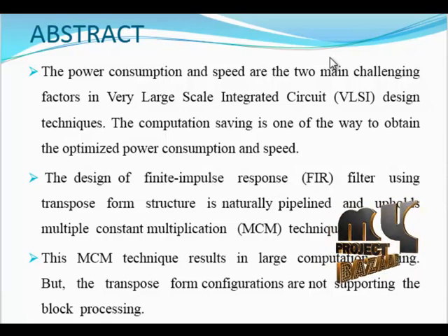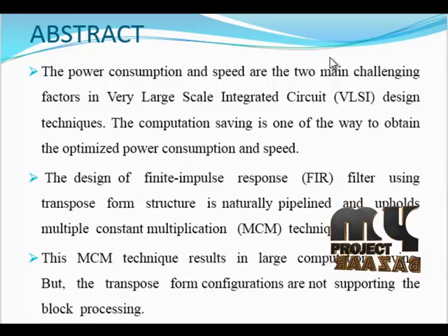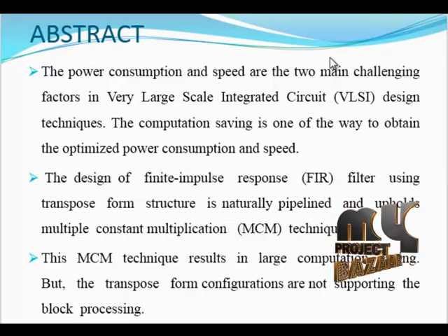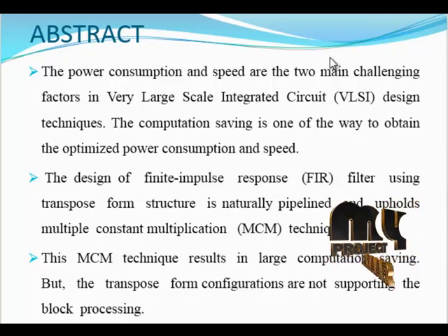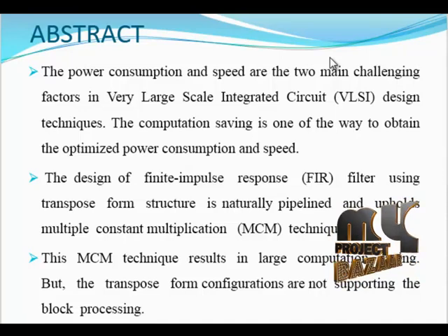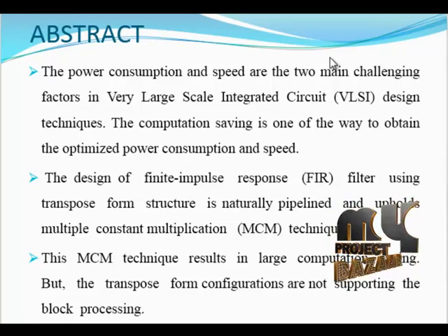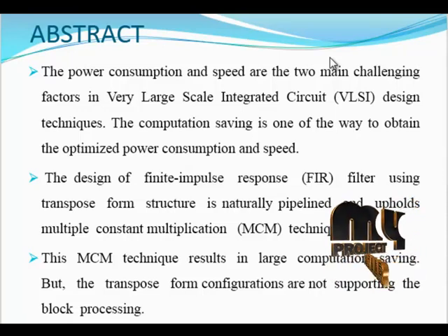There are several applications where the coefficients of FIR filters remain fixed, while in some other applications like an SDR channelizer, separate FIR filters of different specifications are required to extract one of the desired narrow band channels from the wide band RF front end. These FIR filters need to be implemented in a reconfigurable FIR structure to support multi-standard wireless communication.